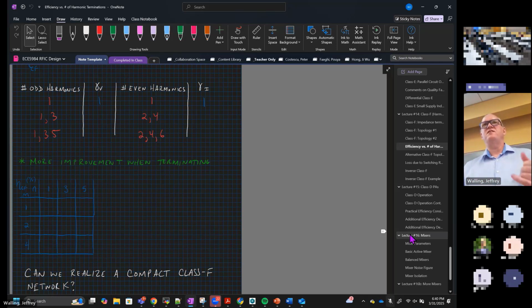The device needs to be able to produce the power that you require plus any power that's required for the parasitic losses, current division, matching network losses, anything. The fact that it's a Class A amplifier is 50% efficient to begin with. So all those things. Got it. Understood. So our end goal is to actually achieve that power for the second part? Yes, that's right.